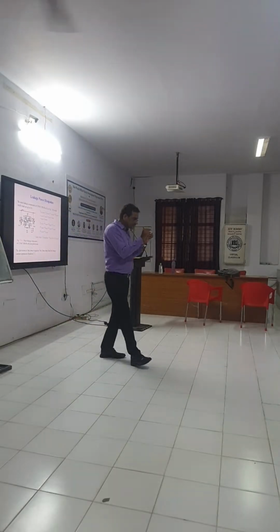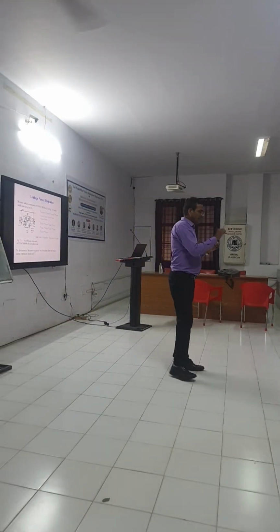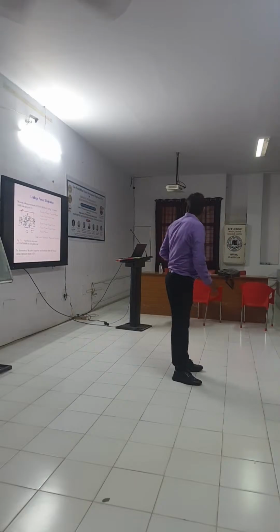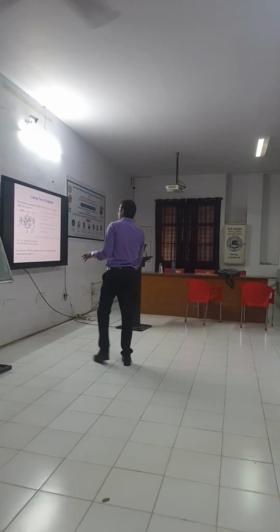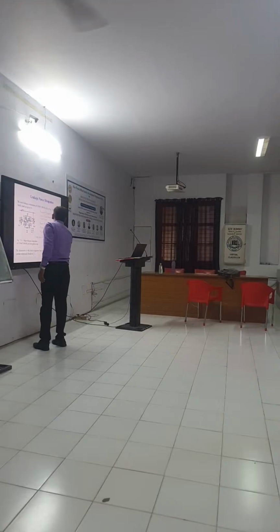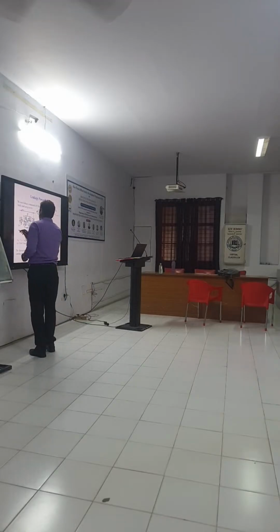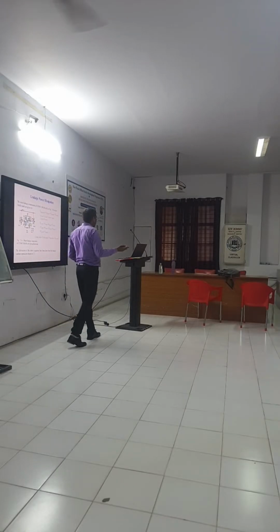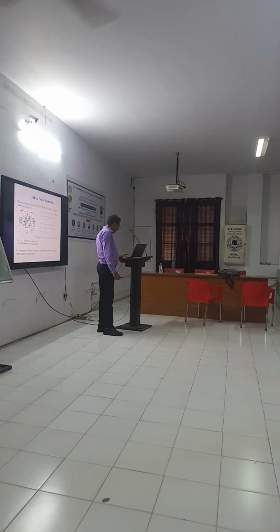So I leakage into VDD. I leakage into VDD, that is the leakage power. So for leakage power, you can write one more line. So here it is okay. So P leakage is VDD into I leakage, and I leakage total we got.